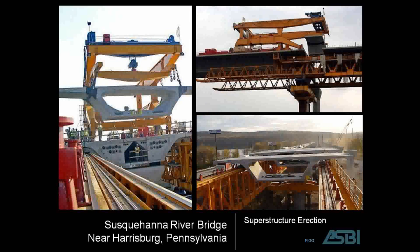Some more photographs of the construction. Here on the upper right, you will see the segment loader placing the last segment of the span. The segments are gapped open 4 or 5 inches, and then epoxy is applied to each segment. Then they're temporarily post-tensioned together to squeeze out the epoxy.